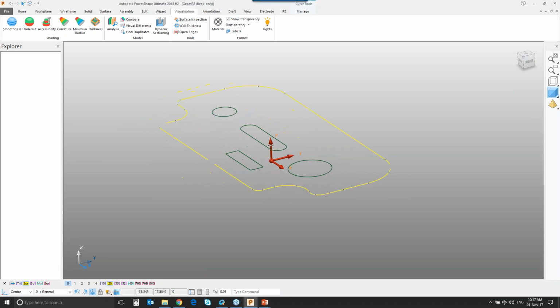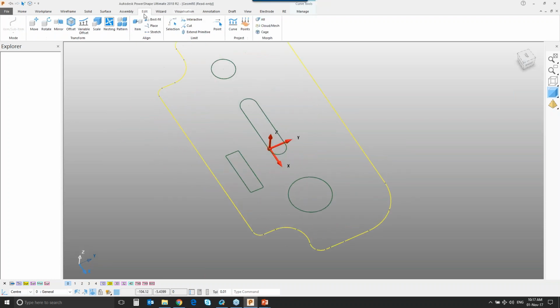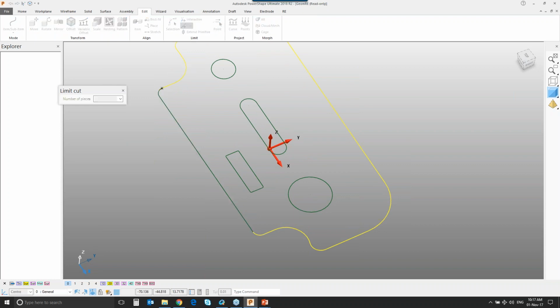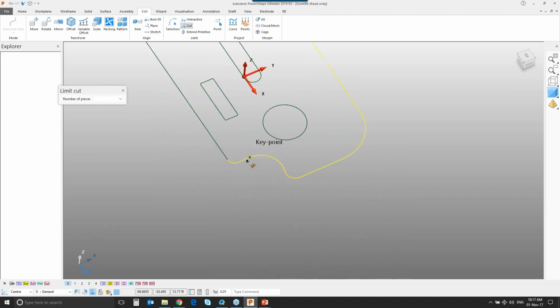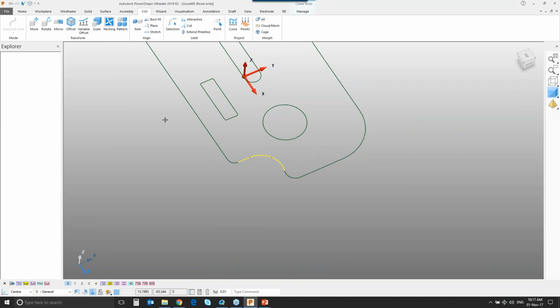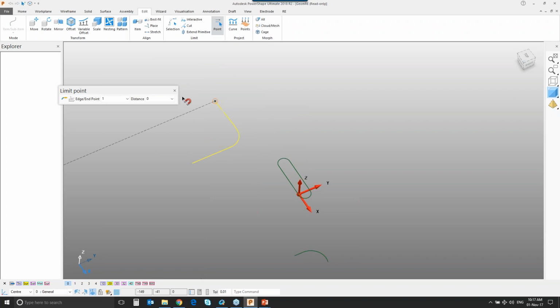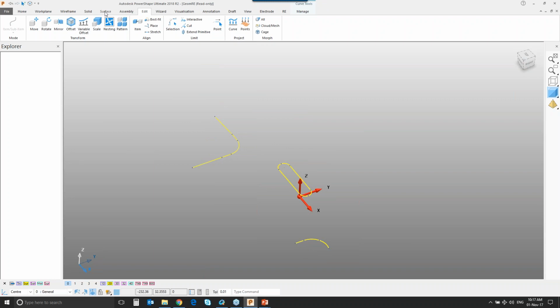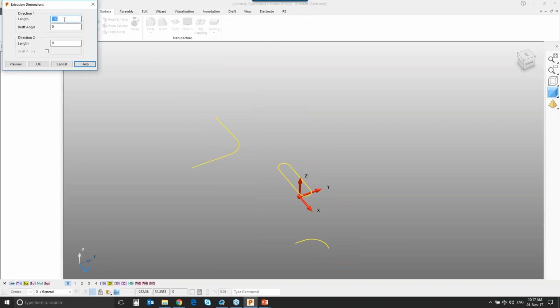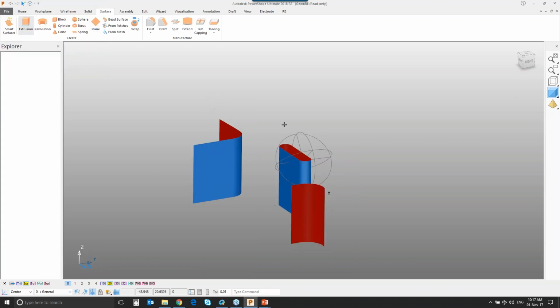Okay, and it's easy enough for me here to go in and start to break this into key regions. So I can select this, go for the edit page, and simply cut this into key entities. So here and here, here maybe, and here, and then look to extend those. So if I select everything except this, this, and this, delete those, I can then go on to extend. So I'll just quickly grab and drag an end, drag another end, and so on. And then of course I can select all of this, turn it into an extrusion in both directions, and we have that region done.